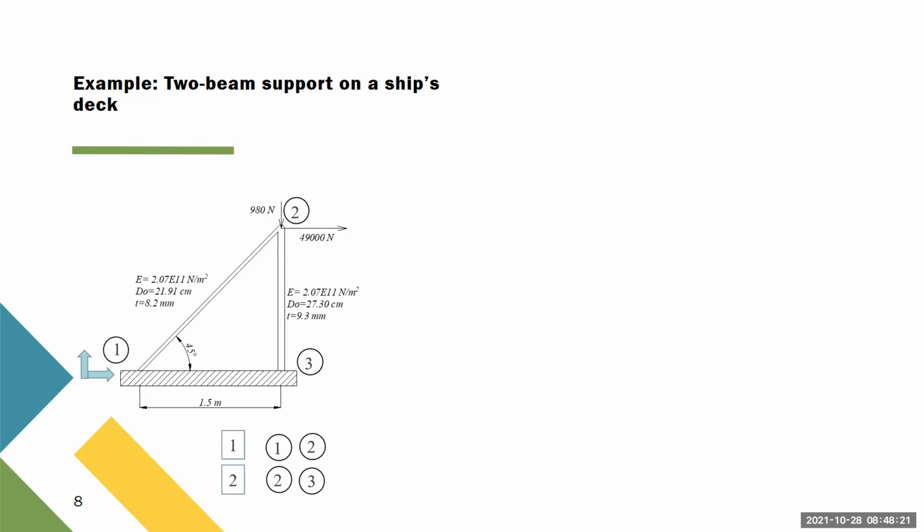Okay, so there are different ways to discretize this. This is one. So I'm defining joint element 1, which goes from here to there. So basically, this is my local reference system for element 1. And this is the second one, goes from 2 to 3. So this is local, and this is local.